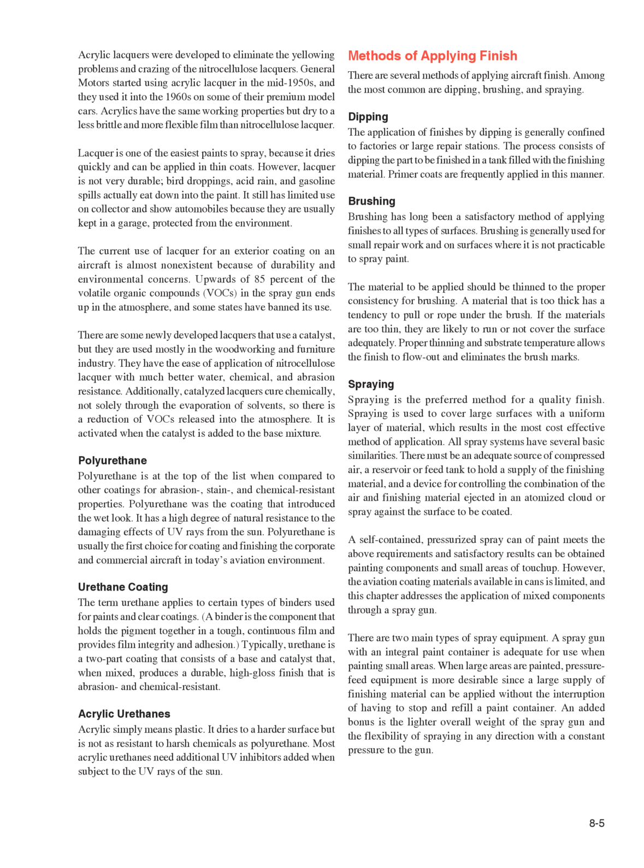Dipping. The application of finishes by dipping is generally confined to factories or large repair stations. The process consists of dipping the part to be finished in a tank filled with the finishing material. Primer coats are frequently applied in this manner. Brushing. Brushing has long been a satisfactory method of applying finishes to all types of surfaces. Brushing is generally used for small repair work and on surfaces where it is not practicable to spray paint.